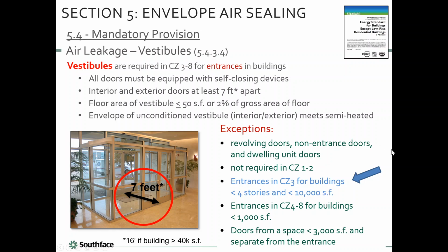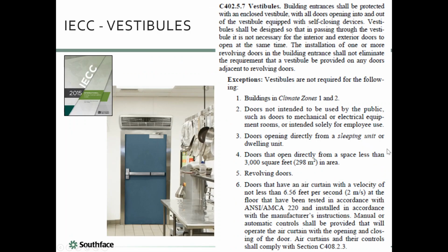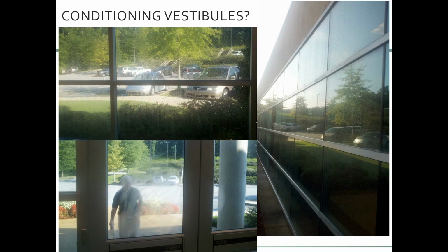I would also suggest that people tend to want to condition them. You're allowed to condition them. We try to encourage designers not to condition them. Really, just let it be a buffer space. When you condition that and the outer door's open, guess what happens to all the conditioned air? So they still provide some good, but it's much better, in my opinion, to very indirectly condition them or under-condition them. Here's, again, what I just said.